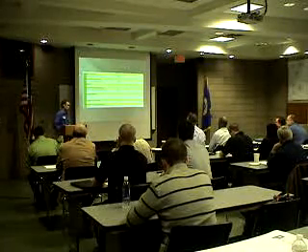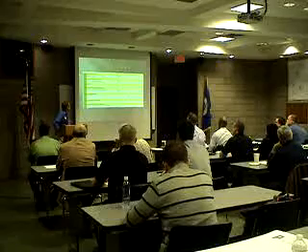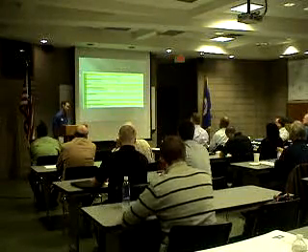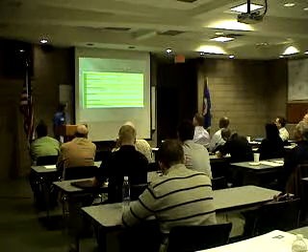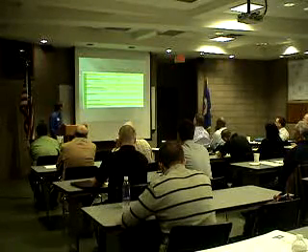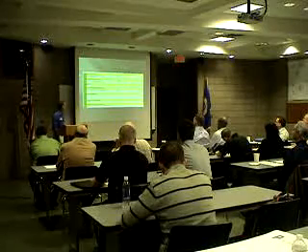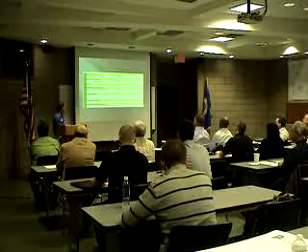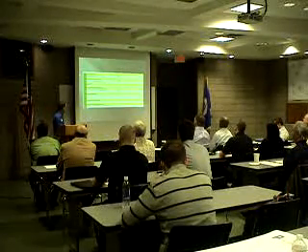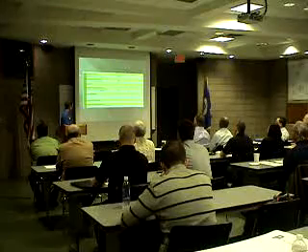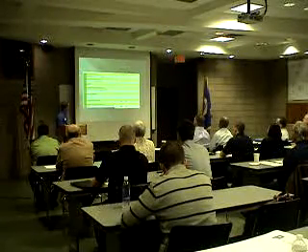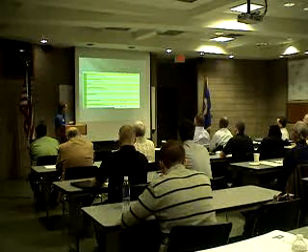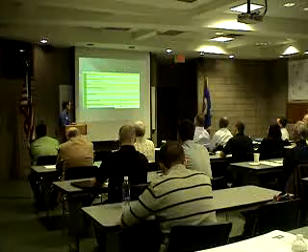Load calc. We did the load calc in Microsoft Excel. Everything from receptacle load in Article 220.14(L), and that's non-continuous. Fixed multi-outlet assemblies, and your office, your largest of the line, unknown receptacle load. Size the receptacle panel with the receptacle neutral, lighting panel with the lighting panel neutral.